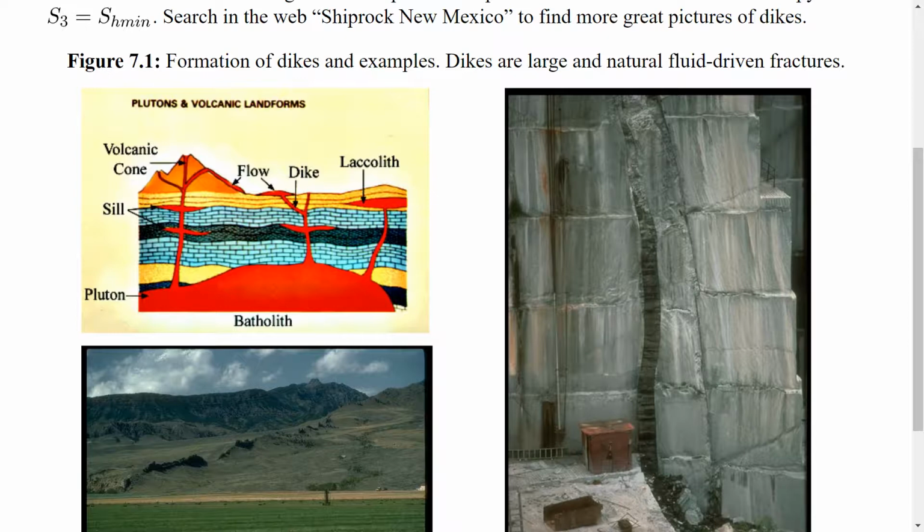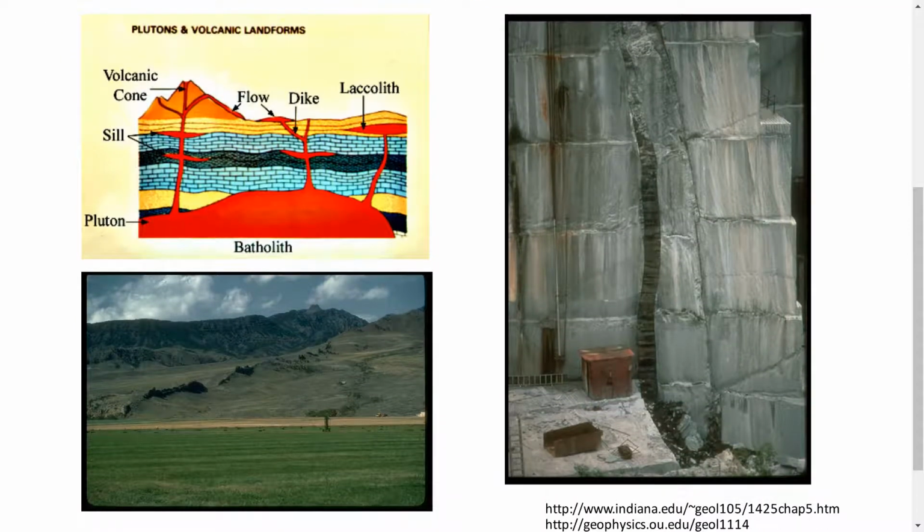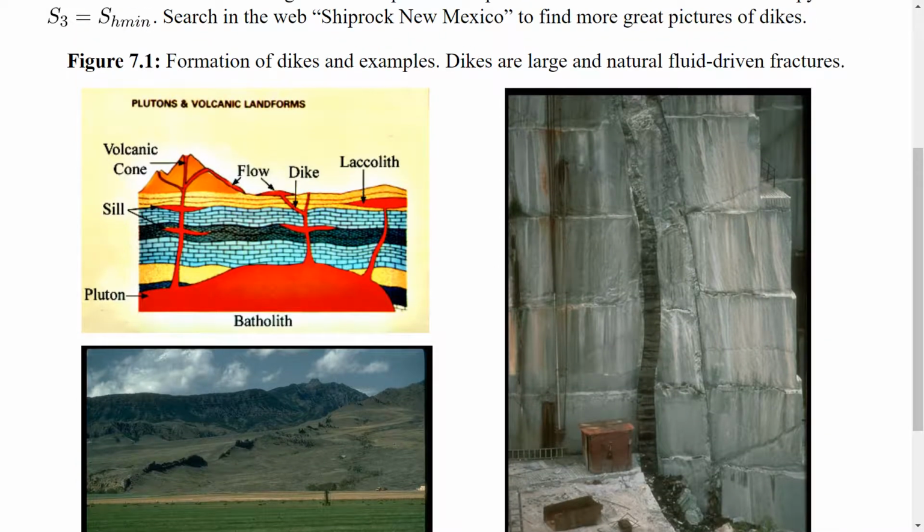And if the minimum principal stress is horizontal, they grow vertically. If at some places the minimum principal stress is vertical, they extend laterally. And in the case of magma, if it solidifies after some time, this is what you see. This is the result. So this is, for example, a natural hydraulic fracture of a magmatic intrusion, and you can see how it grows up in this direction. So in this case, the fracture, what do you think it is? Is it horizontal, is it vertical?